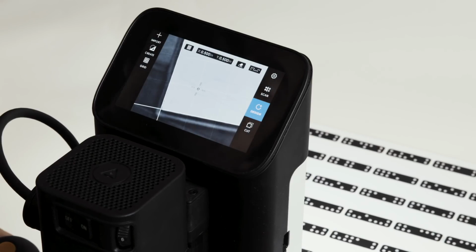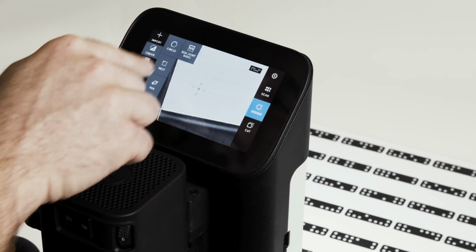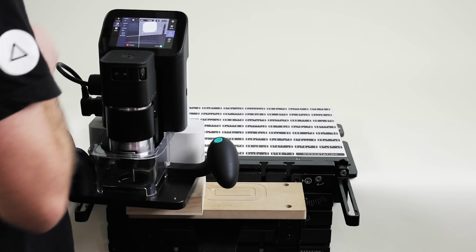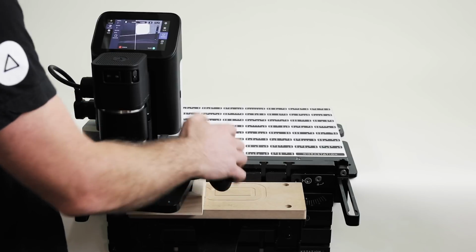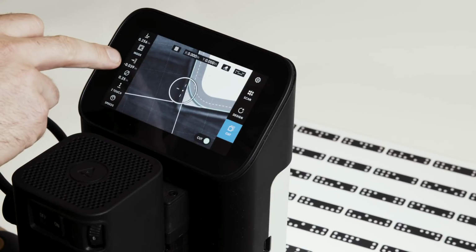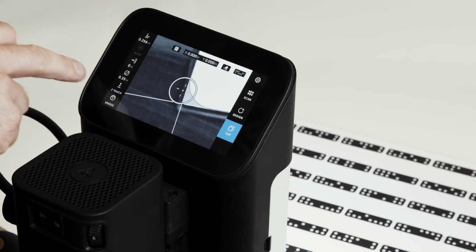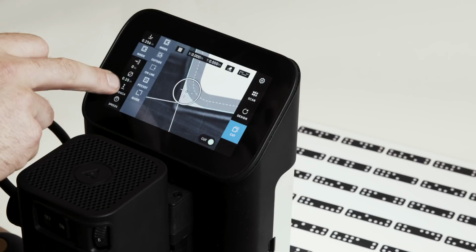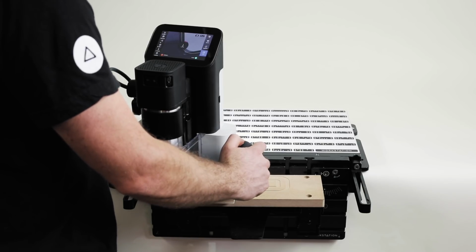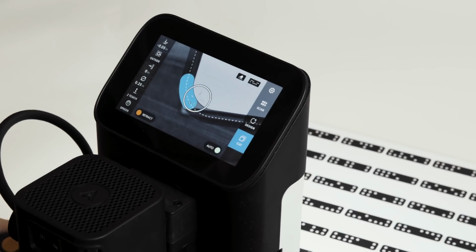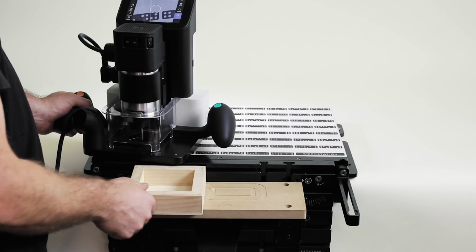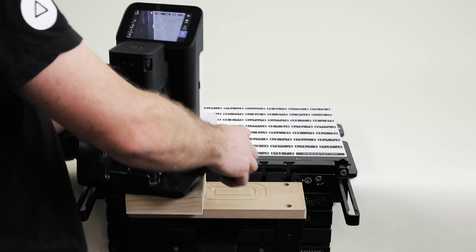So at 1/2 inch increments, I can go in and create a shape, 2 inch by 2 inch, 0.5 inch radius. Done. So if I wanted to come in and round this corner, I can just do this right here and go to cut, no offset, and make that an outside cut. So I could then just round that corner. I'll do an air cut just to show you what I mean. So that could round that corner very quickly and easily using grid and making the most of quite coarse grid increments.